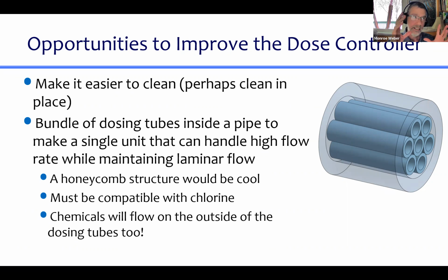And that way, when you need to clean it, you would take that whole bundle of tubes offline and you would soak the whole unit at once as one unit in vinegar. You could imagine a system where you have a pipe that's 2 inches in diameter with a cap on the end that's full of vinegar, and you just drop this tube down in that bath of vinegar and clean it that way. That's a design that's waiting to happen.